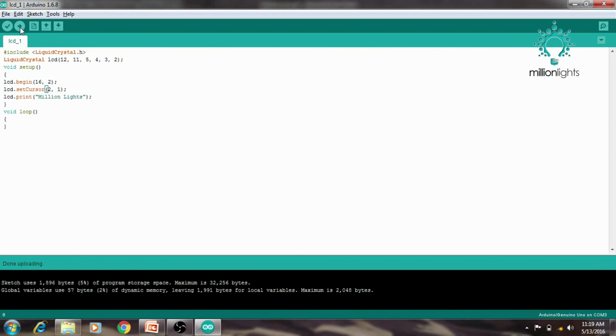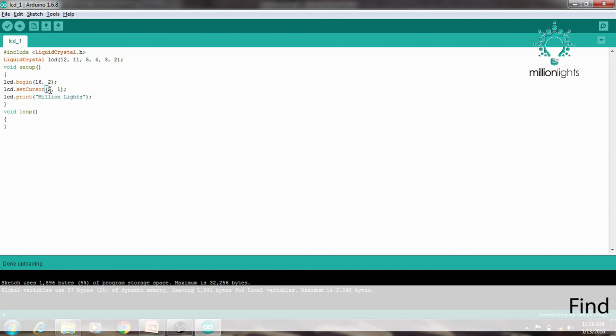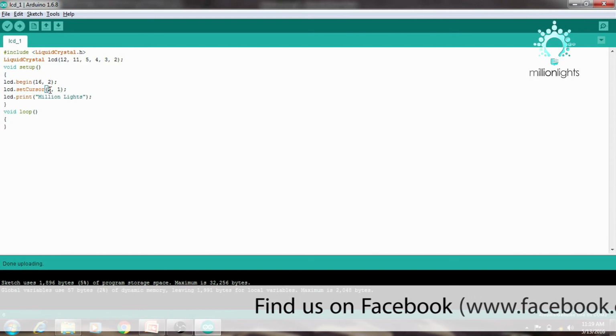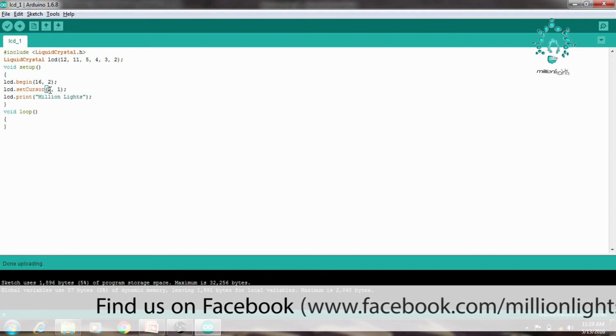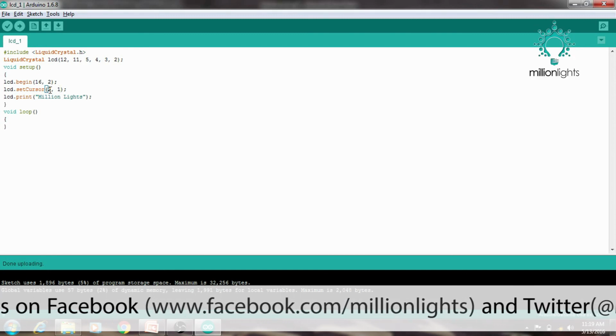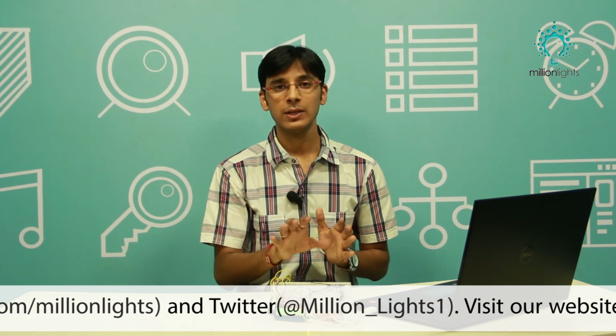So lcd.setCursor(5, 1) or (5, 0) is okay, that means it will start printing from the sixth slot. It is always columns and then rows when we talk about the LCD, and it starts from 0. If we keep this in mind, then we can print anything at any place on the LCD, we just have to calibrate it from 0.